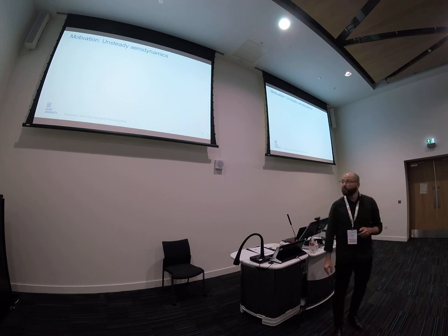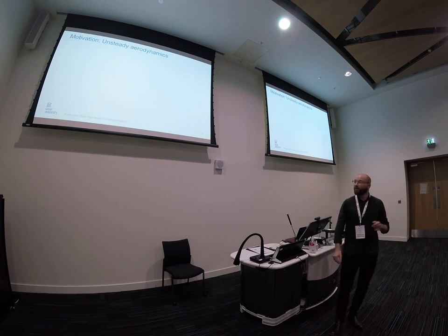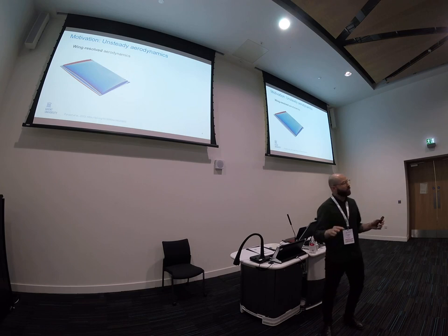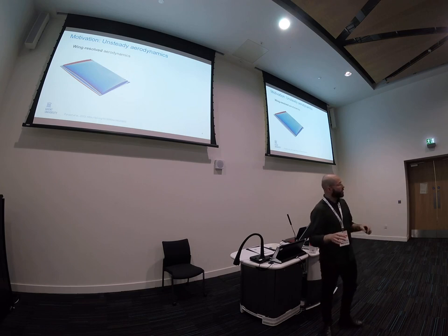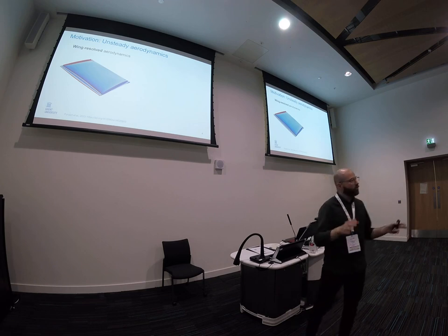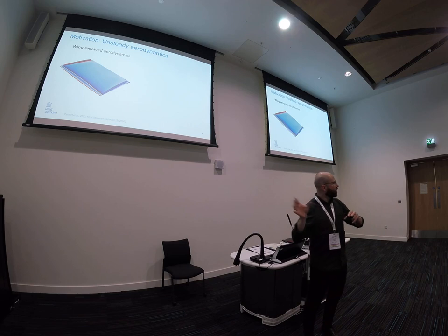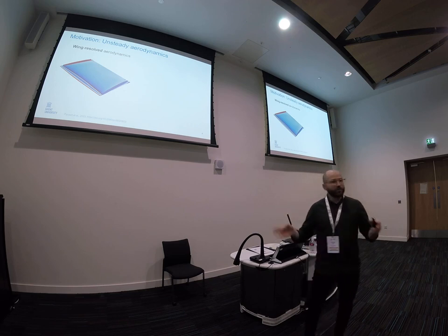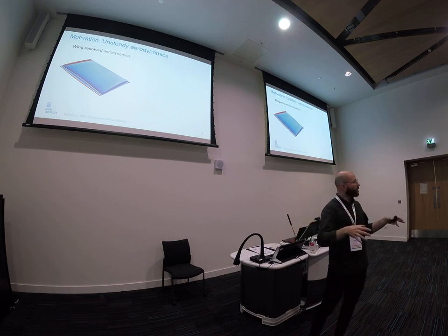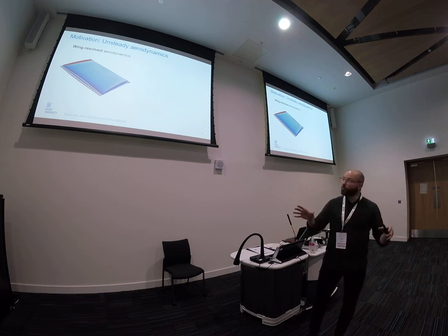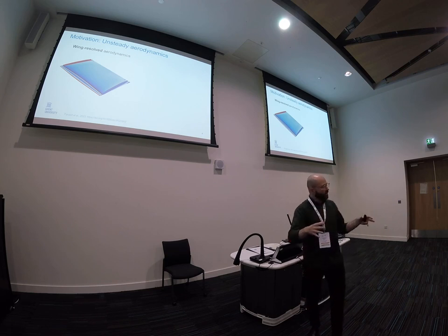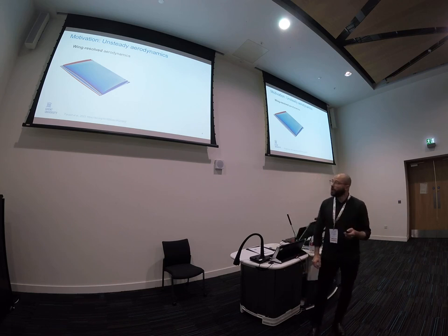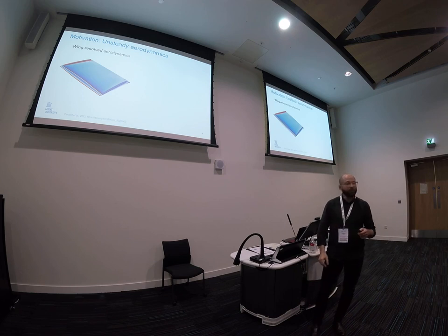We have maybe two high-fidelity approaches, let's say. We can look first at wing-resolved aerodynamics, where we focus on the very local flow patterns around the wing. For instance, we can look at the pressure distribution on the wing, and at the induced tip vortices and how they affect the near wake of the aircraft. That would be one approach that focuses on the specifics of the system. For this, I may also refer you to the work of my colleague, Niels.